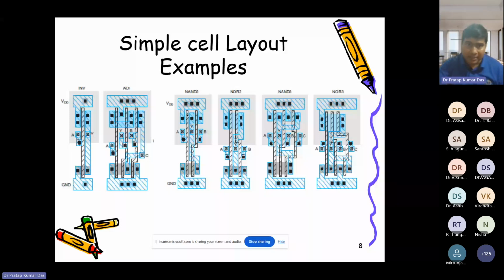That's what you can see here. If you see, the output is connected between the two gates. So each of these is a poly. The output of this cell is connected to the two gates, and the other input is connected to VDD. So basically, these two are in parallel. Whereas here, the output is on this side, then the next one is not connected to anything, and the other one is ground. So this is called series. So this is a NAND gate.